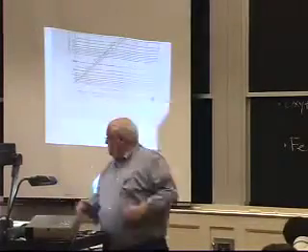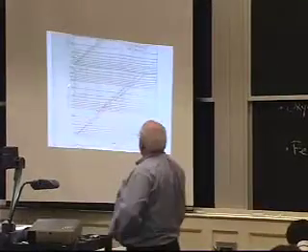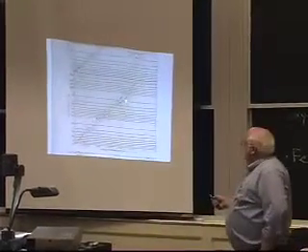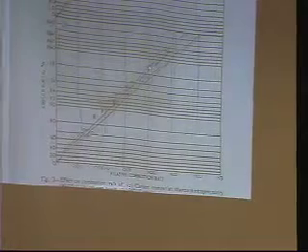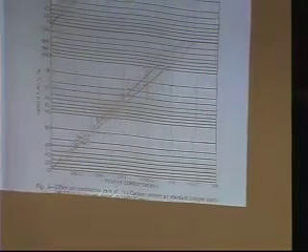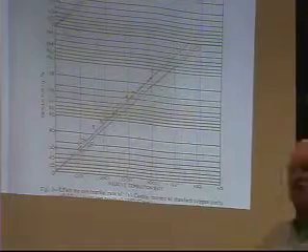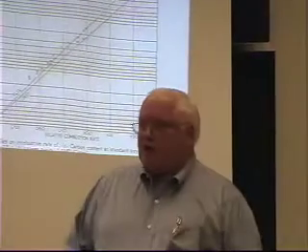By the same token, he also took relatively impure oxygen, and he plotted it on the same type of plot. If he was using very high purity oxygen, 98% or better, he could get a relative combustion rate of 1. But if he was using 80% oxygen, he would be at less than half that speed, because you have nitrogen in that impure oxygen, and that's part of your gas boundary layer.